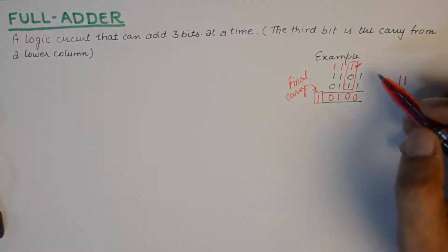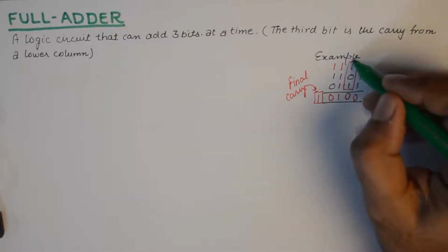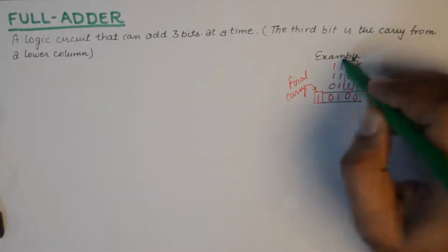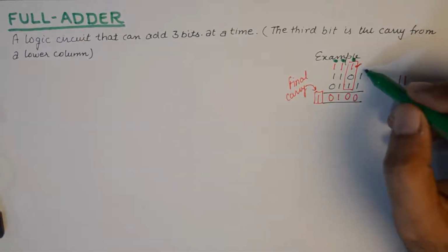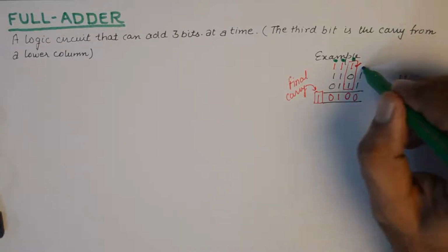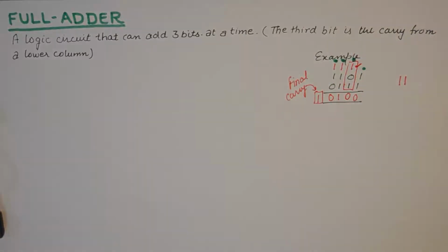But you can very well appreciate the fact that a 3-bit adder is needed at this stage and this stage. The first stage can be dealt with a half adder. So a full adder, full adder, full adder and a half adder can be used at the least significant bit's place while adding. So the need for the full adder is completely justified now.